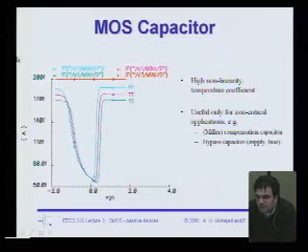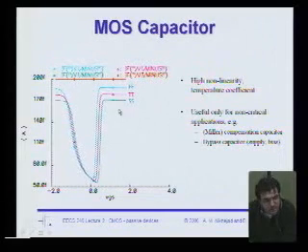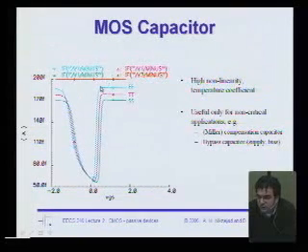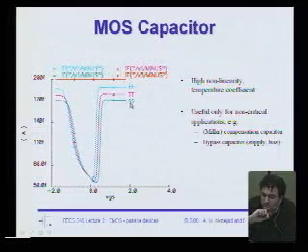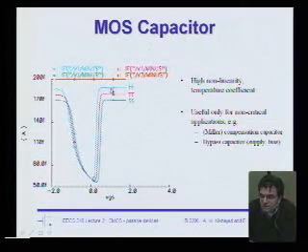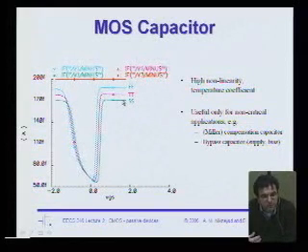You would expect that these two curves on the left side and the right side should line up, and they actually almost do, but they're slightly different, and that's because of what we talked about earlier. Over here you have polysilicon depletion, and you have quantum effects. Polysilicon depletion would actually make these curves go downwards. Quantum effects, probably for such a small change in voltage, you wouldn't see much. What you would see instead is that this curve would not go quite as high as this curve, because the electron position relative to the surface would be different from the holes. So the quantum confinement would be different.